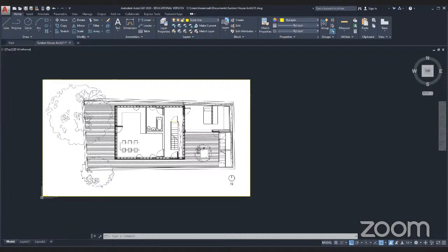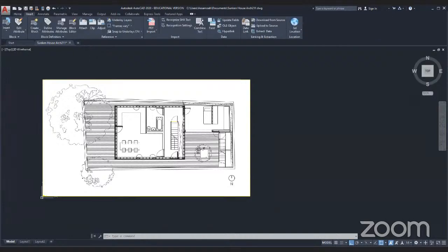So what I want you to do for homework, one, if you have not done so already, download AutoCAD. 2, your architectural drawings for your house, save those out in a separate file. Make sure you label each of the drawings. You want to do it with JPEGs, whatever. And 3, start inserting them into an AutoCAD drawing. Make sure you go through the steps of setting up your layers, changing your units, and then scale these drawings. Try and scale your drawings using an XREF.